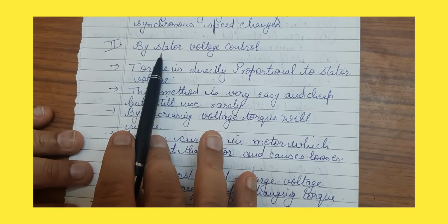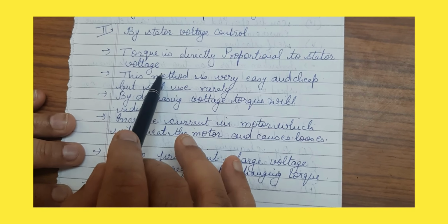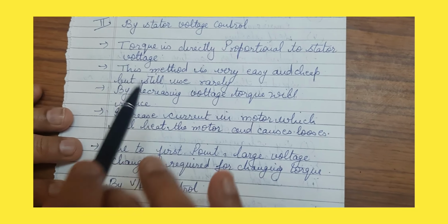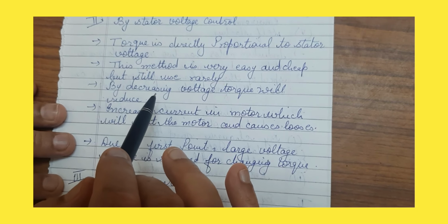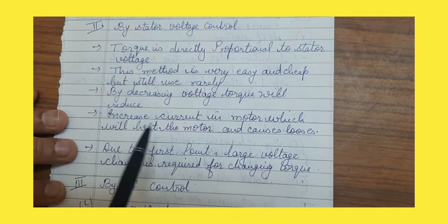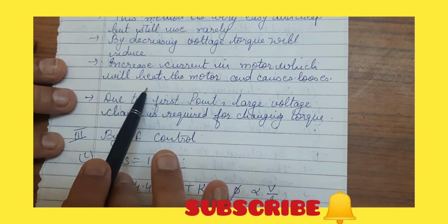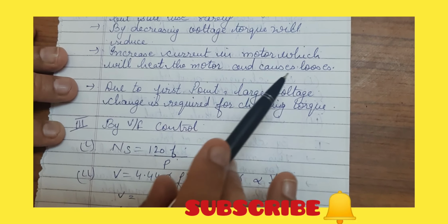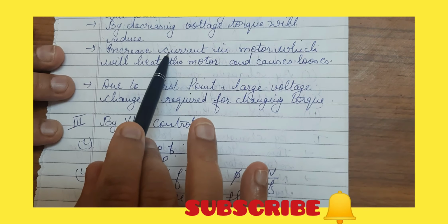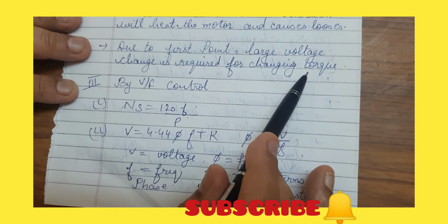The second method of controlling the speed of the induction motor is stator voltage control. In this, the torque is directly proportional to the square of the stator voltage. It is very easy and cheap, but still we are not using this method; we use it rarely. By decreasing the voltage, torque will reduce and current in the motor will increase, which will heat the motor and cause losses. That is why we use this method very rarely. Also, a large voltage change is required for changing the torque.